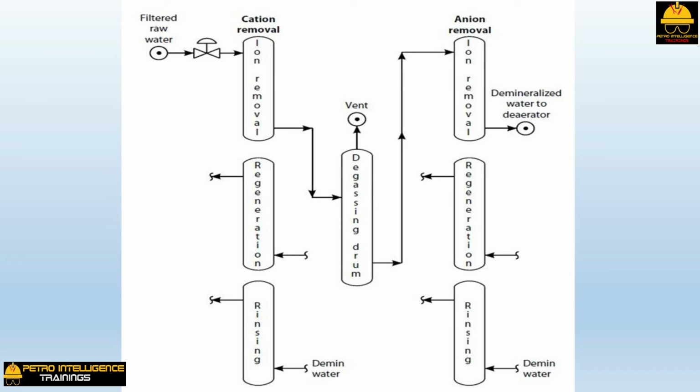It is important to avoid stirring up the resin during the regeneration step. The main objective of the regeneration step is to leave the purest resin at the bottom of the vessel. This will then polish the downflowing water when the bed is returned to its ion exchange service. A slight back pressure using air is typically employed at the top of the beds to hold the little beads in place during regeneration, and works best after first draining the bed down by about 1 foot below the top of the resin bed. It is also possible to lose the beads from the ion exchange vessels during the regeneration and washing steps if the resin beds are not held down properly during this step.